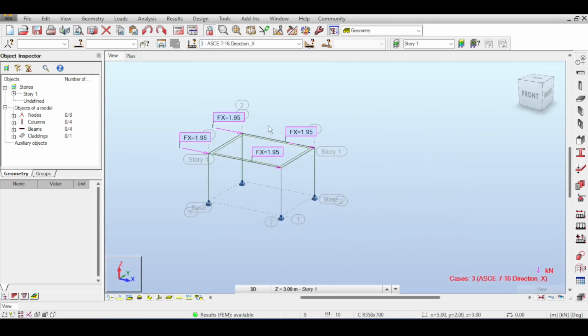Now, I told you before that force-based shear equals CS multiplied by W. And you would think, what is W? W, you might think, is the self-weight of the structure, and you are partially right. W, as a matter of fact, is not only the self-weight, but it's the self-weight and the dead load, meaning all the loads that are not expected to move. Now, in some codes, you will have to even include parts of the live load in your earthquake calculation.